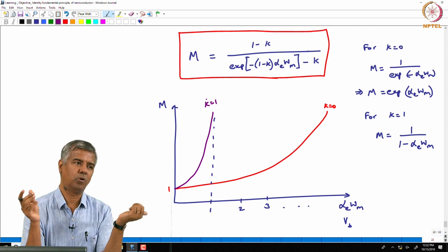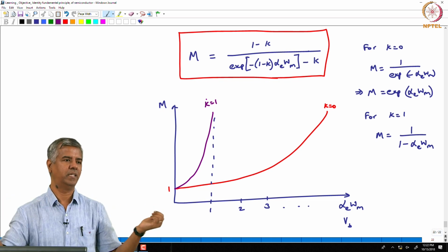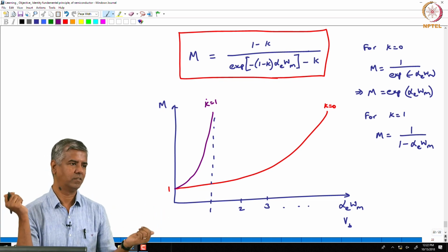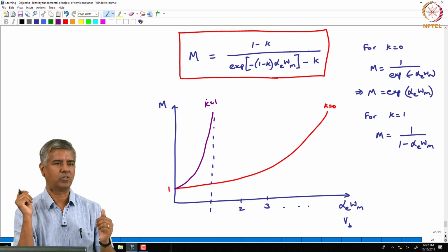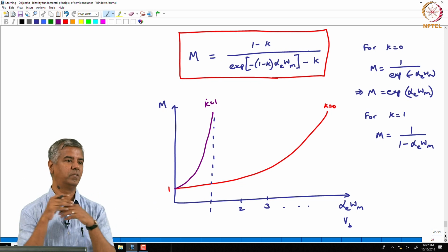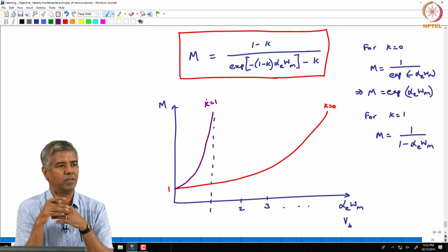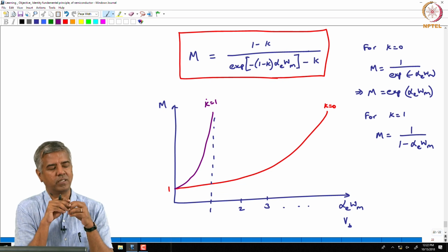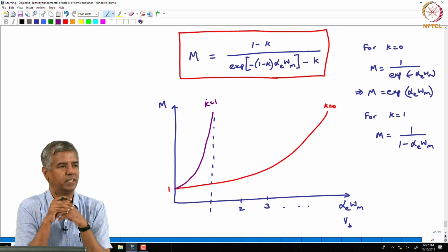Now, if you do it with holes, it becomes even more noisy, because those are two different independent processes in terms of creating that avalanche. So, you have much more noise, much more chaos essentially happening when you have both of your carriers generating avalanche independently. You have a question?